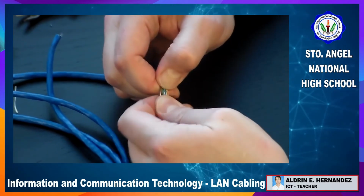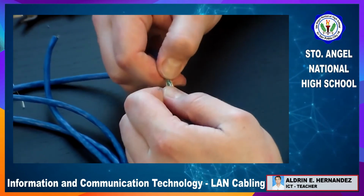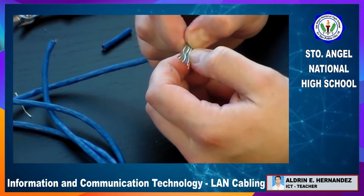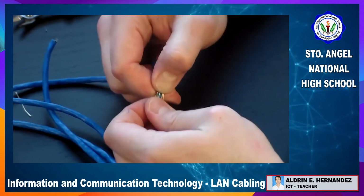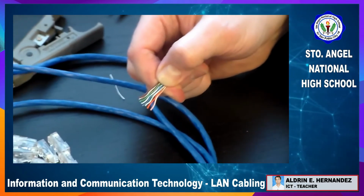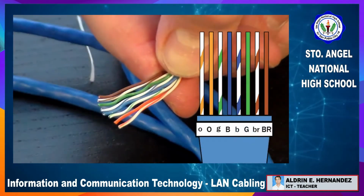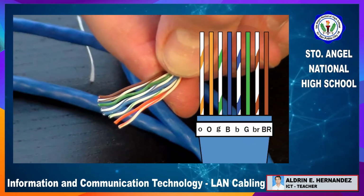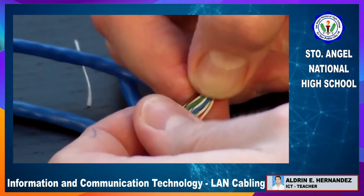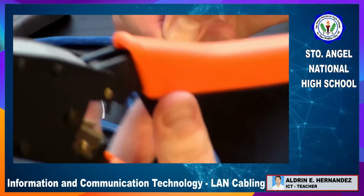Now once you get them organized, there's a specific sequence in which they need to go in. You'll see the diagram come up on the right hand side of your screen momentarily. Boom, there you go. Alright, here comes the diagram. Excellent. Alright, so now grab your FD 500R crimping tool and cut off some of the excess wire because we don't need that much to go inside the connector.